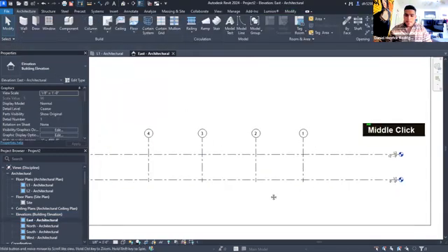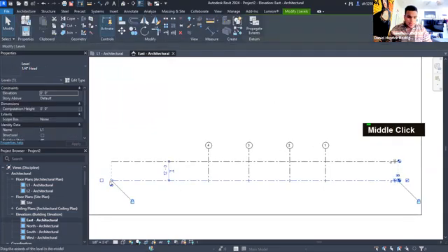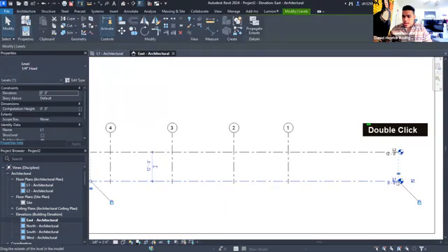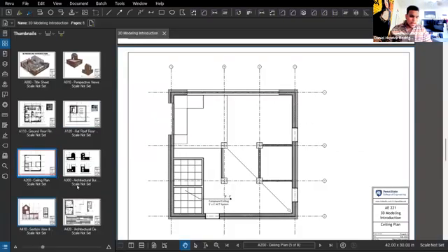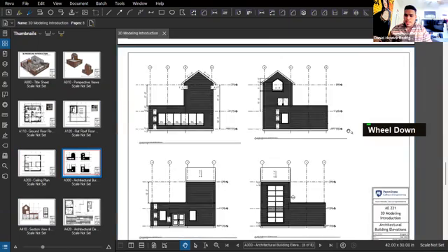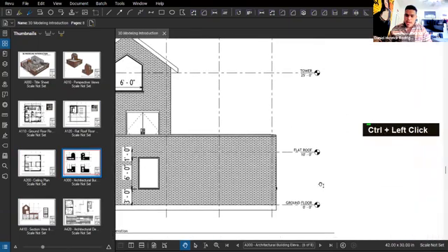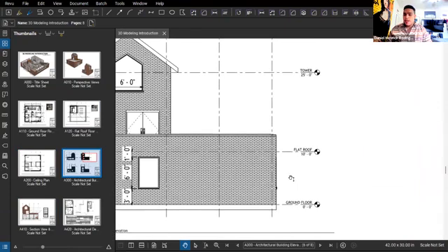These grid lines, right, they go really far off. So what you can do is, like I said, use those hollow circles to move them a little bit closer in. And we're essentially just going to try to copy what we have on our drawings, right? So if we go back to the drawing and we go to the elevations here, we're going to be able to see that we have a ground floor, a flat roof, and a tower, okay? Revit always gives you 2 floors, because to build a wall, you need a base and you need a top. So Revit automatically starts with those 2. We're going to make sure that we rename what we have, and then we're going to add the new one in, okay? So we have ground floor, flat roof, tower.